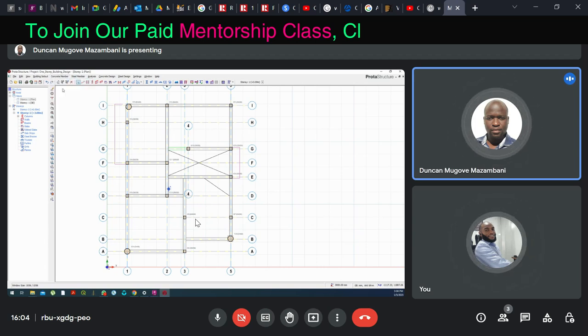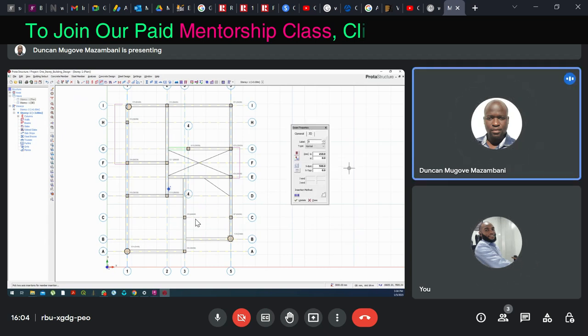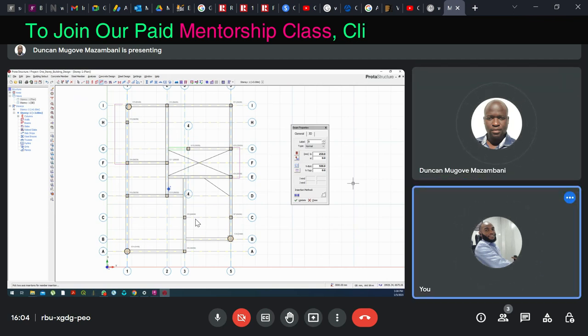Now a dialog box will appear for you. Now you have to input your width of beam and your depth of beam. Your width of beam should be the same as your width of wall or your column. So that B, where it's showing B at 250, should be your width of beam. In this case, it is 225, which is what we use. Now your depth of beam, the minimum you should know is 450. That is the lowest depth of beam that you can first of all assume.